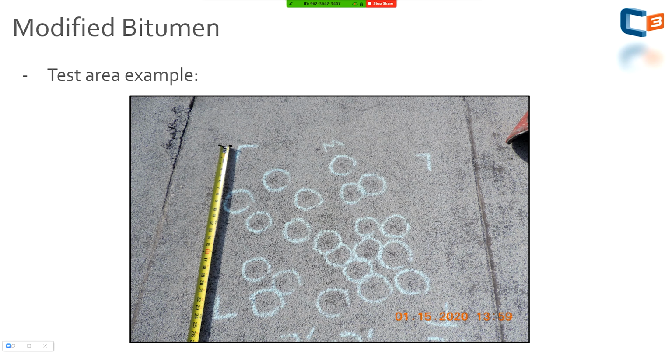But on a flat roof system, you're thinking these courses are very, very long. They're 36 inches wide. If you have damage to that course, you can't really just cut out the parts that you want and just repair it. It'd be all patched up. So for that reason, we usually do a 2x2 test area on all commercial roof systems. This is 1/25th of a square.